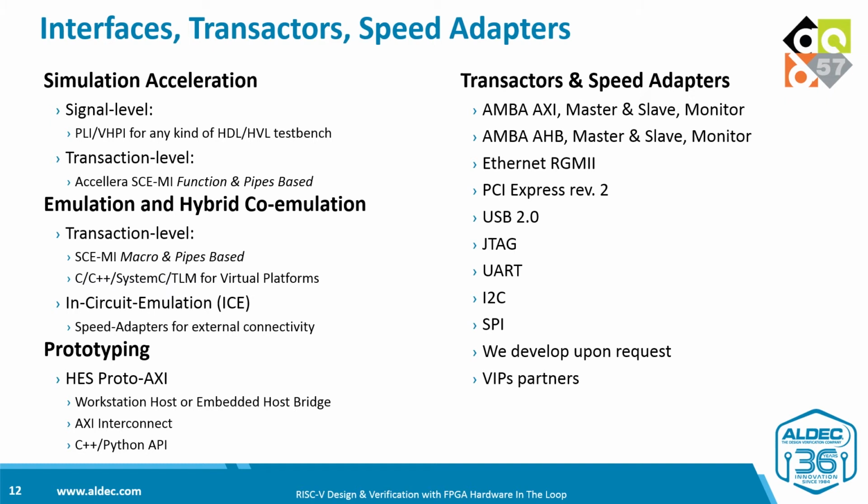Emulation and hybrid co-emulation are supported by a transaction-level interface, which is compliant with the Accellera SCE-MI standard. Additionally, Aldec provides SystemC and TLM wrappers to facilitate connection with popular virtual platforms. In-circuit emulation that often requires connection with external devices running at higher clock rates is supported by the speed adapter dedicated features in DVM and also by support of multiple clock domains.